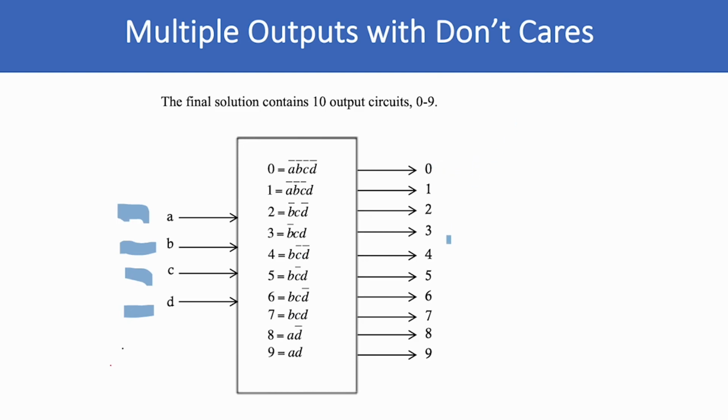So we have 10 outputs, and when any one of these, for instance, when 0000 appears on the input, only this one is going to be true, which will be a 1. And whenever we have a 9, which will be 1001 on the input, the 9 will become true. All the rest will become false. So you can put the binary combination of 0 through 9, and each of these will individually come up, telling you whether you have a 0 all the way down to a 9.